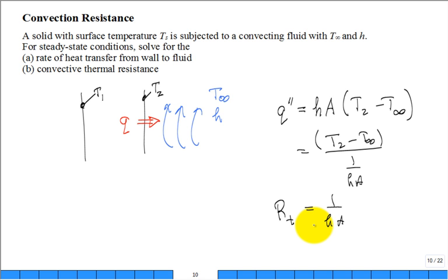Area goes up, the resistance goes down. So we could put a little network here and have 3 nodes. Just like voltage was for an electric network, we have temperature at each of our nodes in a thermal network. So we're going to have T1 at that node, T2 at that node, and T infinity out here. And what do we have? We could have flow of heat through that slab.